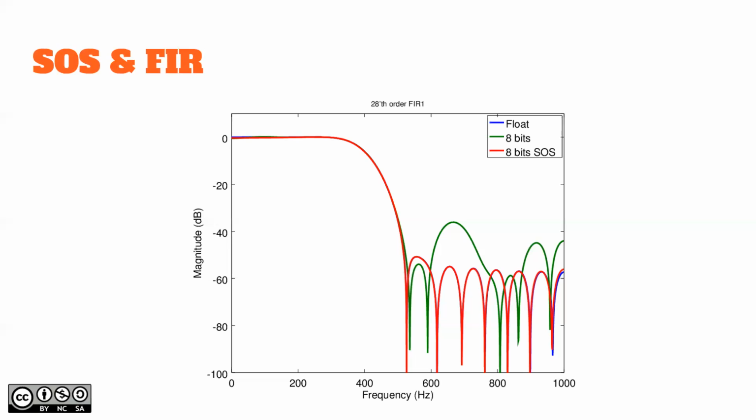For the FIR system here, wouldn't first order systems have even less error? Yes, but you cannot do with first order systems if you have complex zeros and poles. You must pack them into complex conjugate pairs. Otherwise, you are calculating with complex coefficients, which don't really make sense. So they must be complex conjugate pairs.